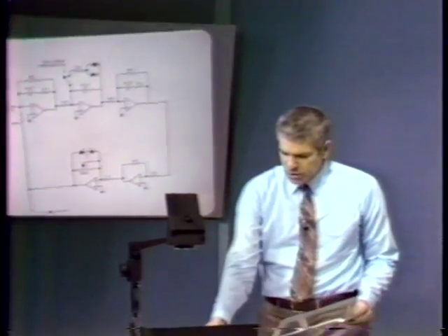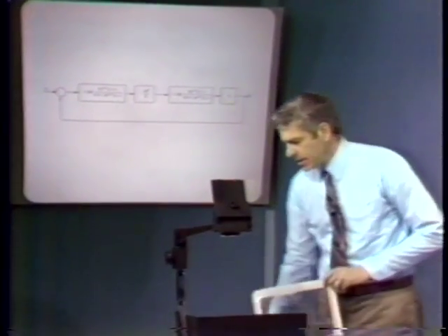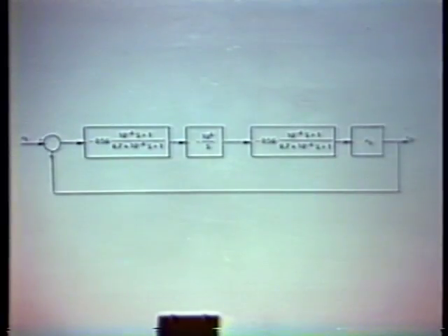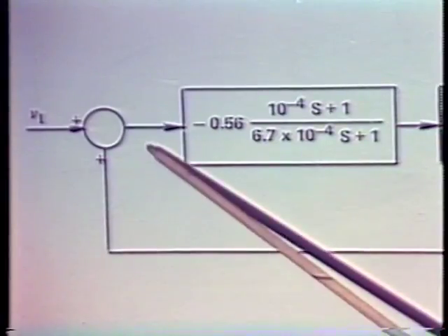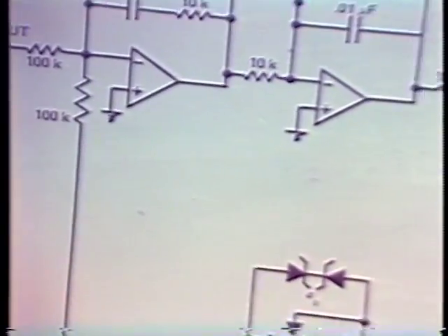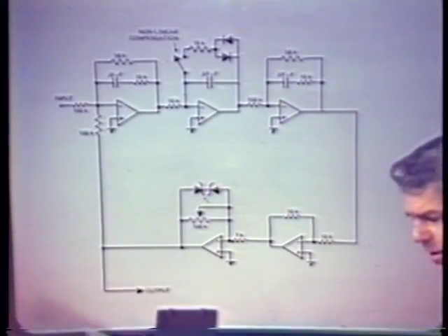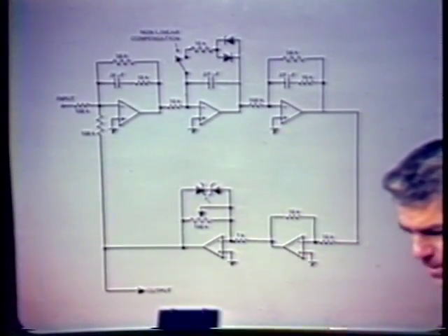There's a very nice one-to-one relationship between the block diagram and the circuit that I'd like to emphasize. Here's the input and the fedback signal that are really summed, and we saw that earlier. The 2 input resistors here and here perform that summation.